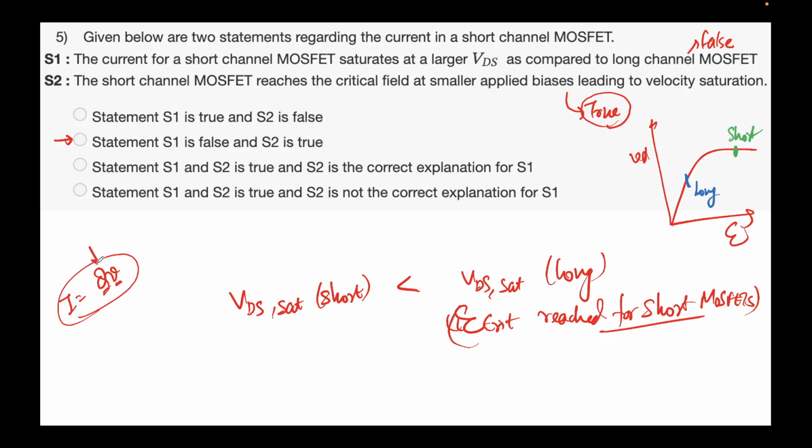This Q is determined primarily by your gate. This is the inversion charge. This Q is nothing but your inversion charge. This V is being determined by the lateral field. That is your VDS. So this is determined by VG primarily. This is determined by VDS. So drain current is a manifestation of both of them. All right, so yeah, that is the complete picture.